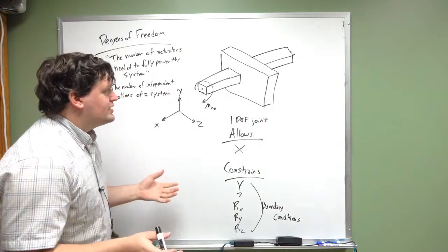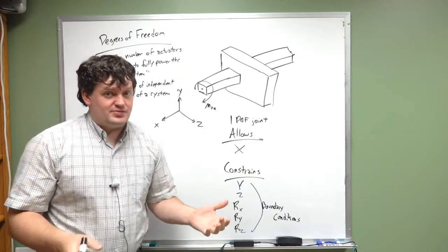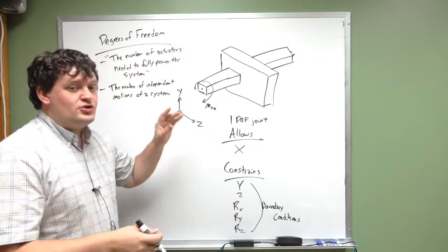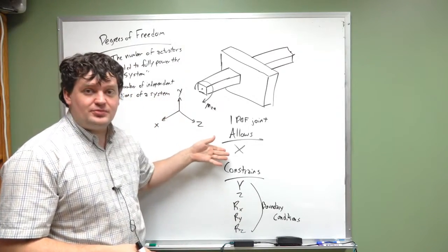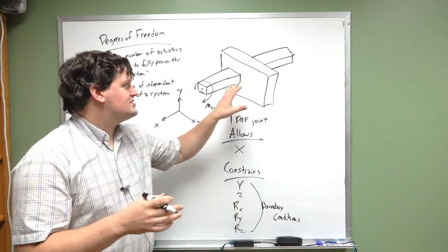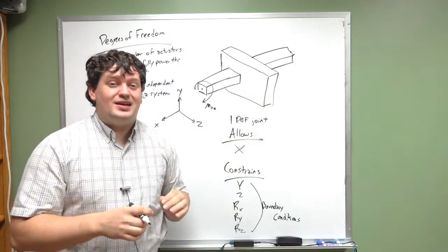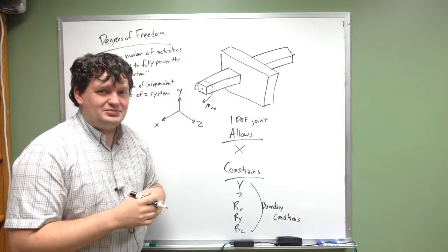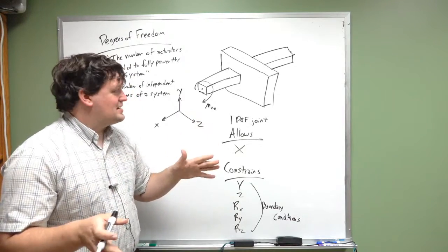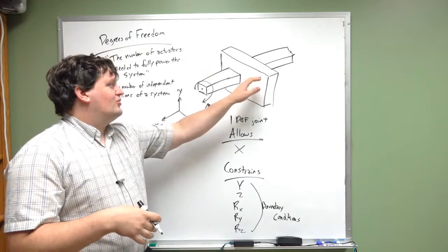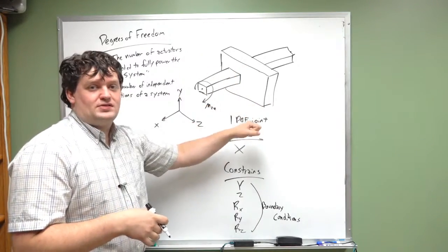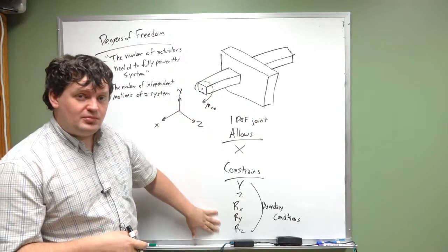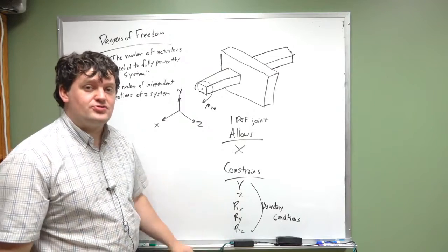So as we're looking at joints, we're really looking at degrees of freedom here, because degrees of freedom tell you where forces are being transmitted. If you have too many degrees of freedom, you don't have as many forces that are being transmitted through a joint. In some ways, that makes the joint stronger. We'll talk about that in a bit. But when you're looking at joints, the number of degrees of freedom are inversely proportional to the number of forces that can be applied as boundary conditions.